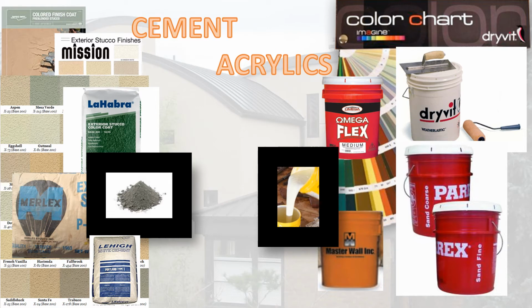Finishes for stucco can be put into two basic categories, cement or acrylics. Each has pros and cons, and no finish material is right for all projects. Cement finish comes in a bagged powder form, while acrylics come in pails. We tend to say cement finish cures to a set and the acrylics dry to a set. There are many differences between the two finishes, and regional practices play a large role in which and why each is more popular in their region.